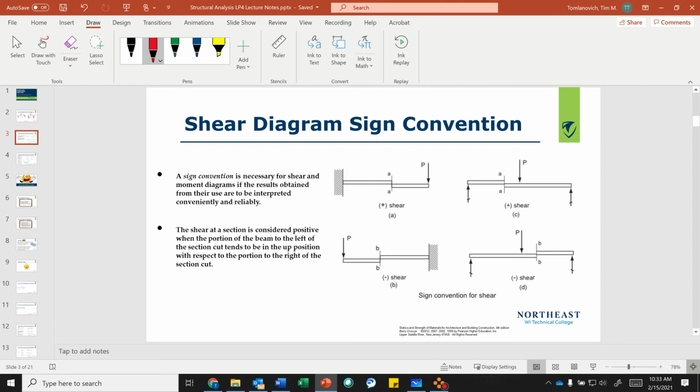These external loads, we're now looking at on the inside of our beam, because when those loads come onto our structural members, they are bending and they want to shear. So we need to figure out what those shear and bending moments are so that in the next learning plan, we can actually size these. We've got to figure out that maximum internal shear and bending. So we're taking those external loads and looking inside the beam, like we're cutting a cross section in a beam, and you're standing inside of it.